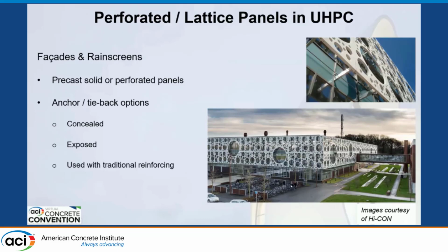These are the panels where they've used some traditional reinforcing. So there's some GFRP bars up in some of these corners where there might be a lot of load or a lot of stress around some of these openings, and so they'll put a few of those bars in there just to stiffen it up and protect this panel. This panel right here is this corner of this great big circle. Or this one right here is the bottom left of this big circle. So that's the kind of application where it makes sense to couple it with traditional